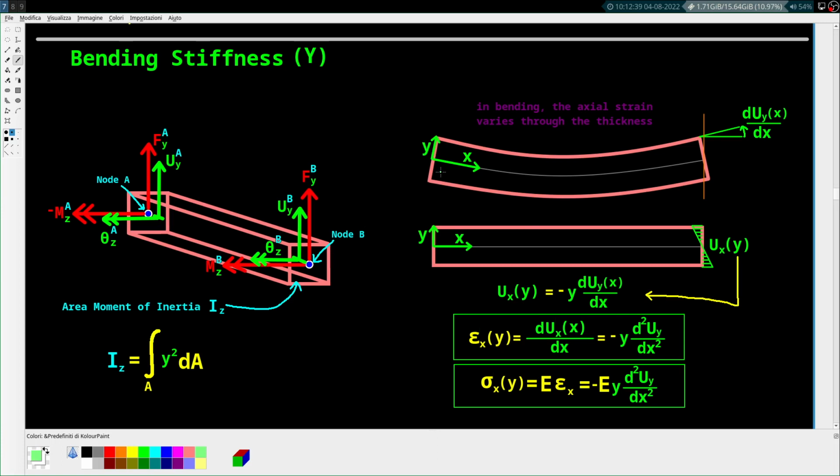And so what's important to also realize is that in bending, that extension affects the axial strain. Well, I just showed you with tension here, compression here. That is axial strain, right? If this gets shorter, that's an axial strain component. And so basically, how you can look at that is saying, well, what is the slope? So the slope that you've caused here is actually the amount which you've compressed this system.